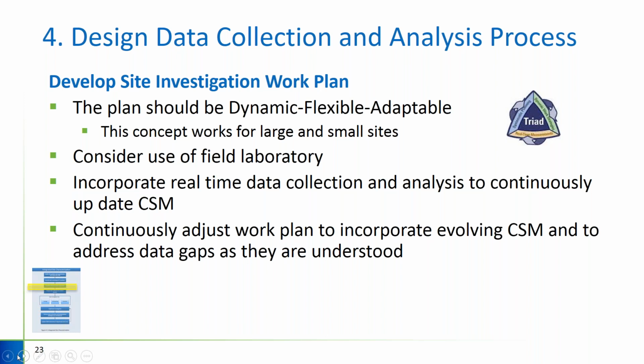Another thing to include in the work plan at this phase is you have to define the parameters within which the field team can make decisions. For example, if you lay out a grid of sampling locations, let's say groundwater grab samples, and you define a grid of 20 locations, it's probably not a big deal if the field team has to move one of those locations by a couple of feet to avoid a utility.